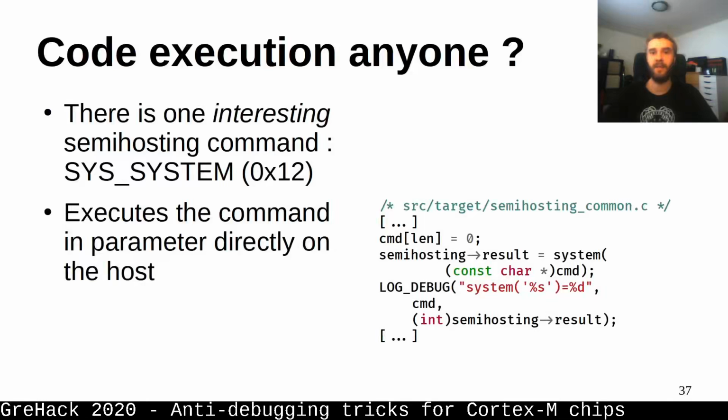It takes an argument from the device, and the host will execute this command using the system call on the host. On the right, you can see that OpenOCD already supports this, and there is no mitigation and no checks about what is being executed.